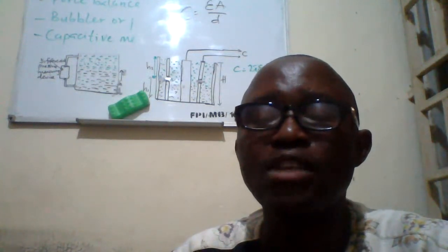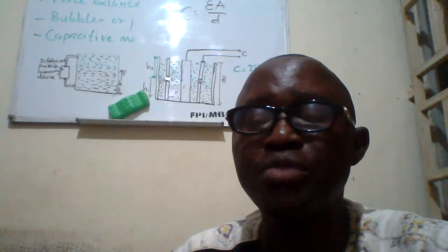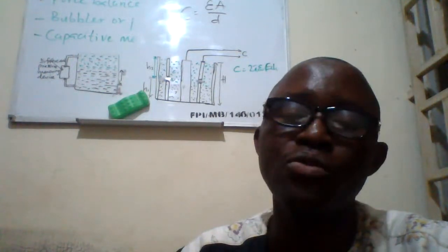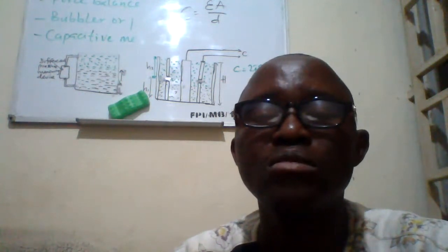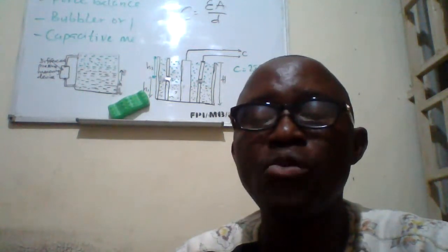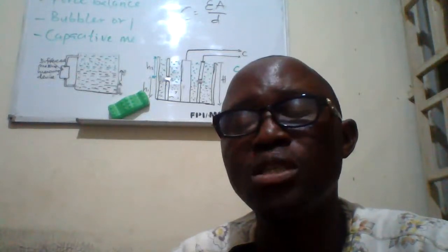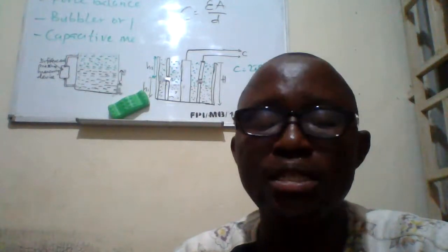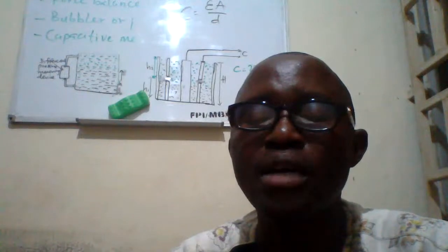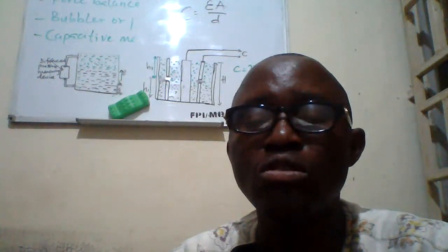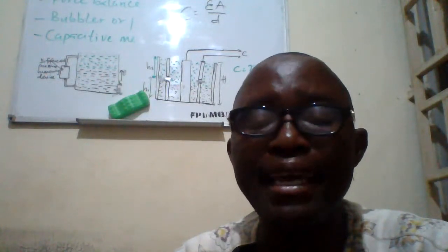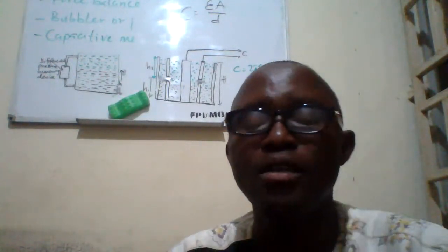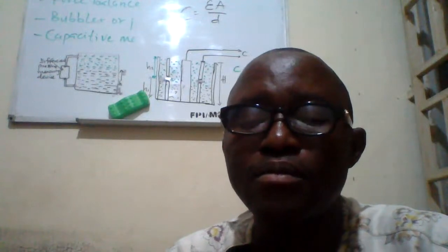The device, a differential pressure transducer, is determining the bubbles that are coming. When the bubbles escape to the top of the liquid, at that point, the pressure of the bubbles is equal to the hydraulic head of the liquid. So that pressure will be used, with the mass density of the liquid, to determine the height of the liquid in the tank. And that is how the system works.